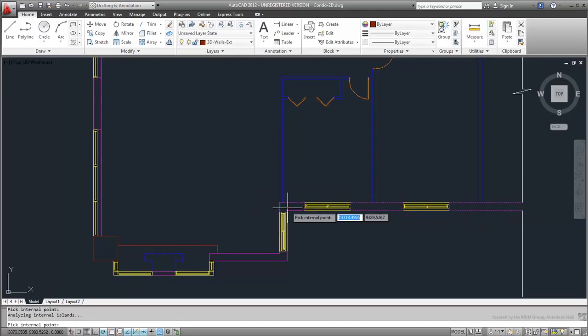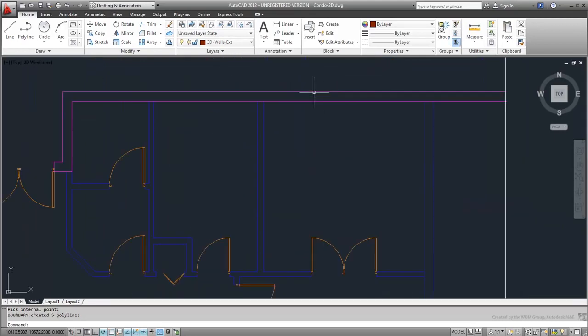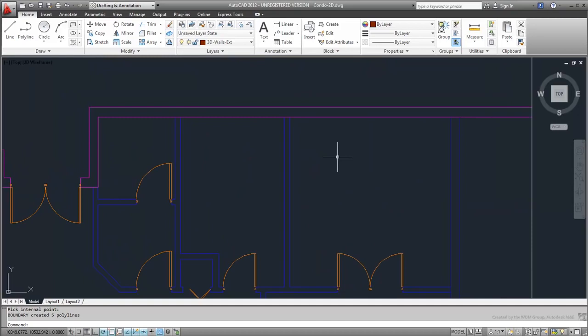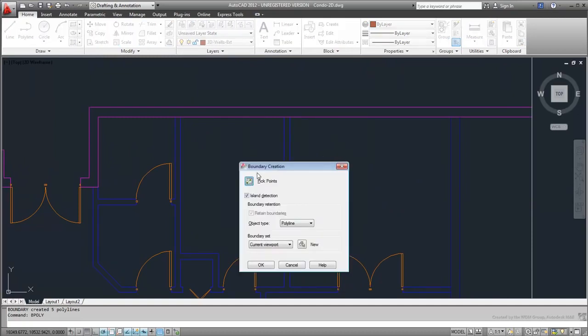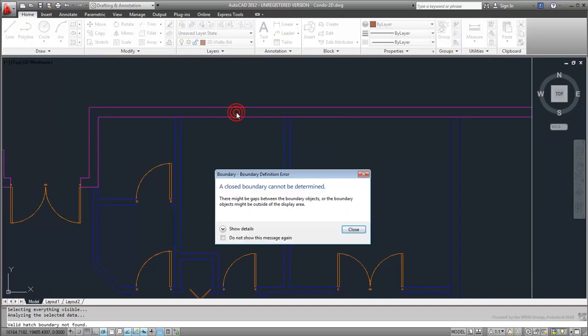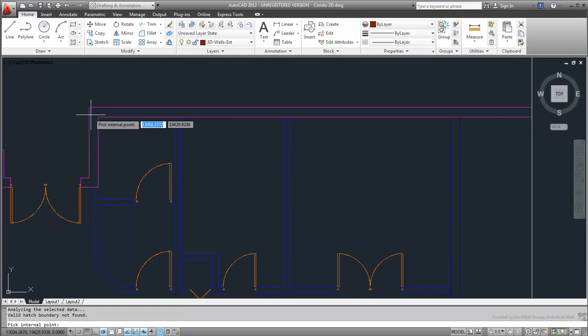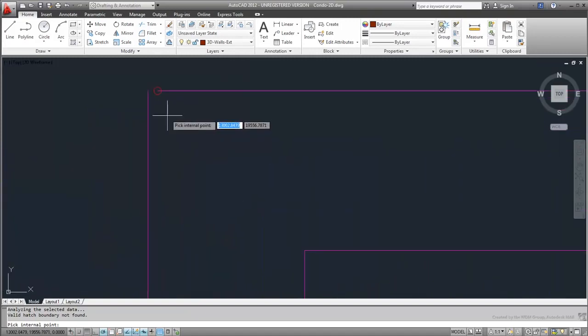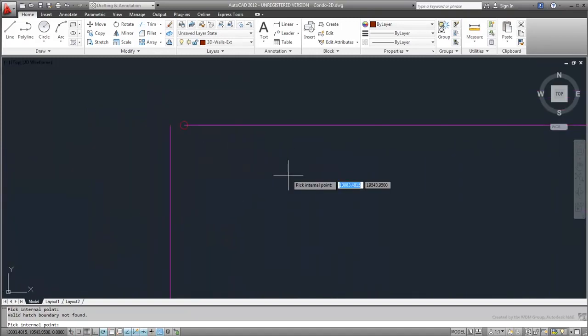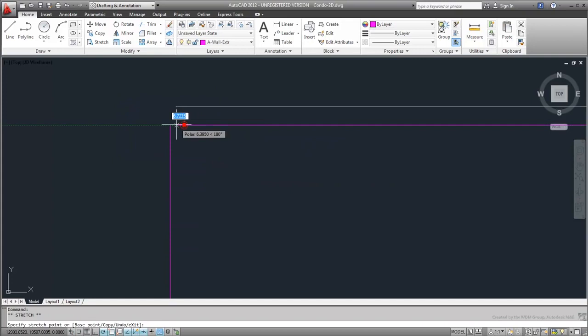For this command to work well, the area you click has to have boundaries. Try the command on the top right wall. Notice the error. It's saying that the bpoly command cannot identify boundaries. A closer inspection shows an opening in the wall. This was left intentionally to show the kind of problems you can run into if your CAD drawing is less than precise.